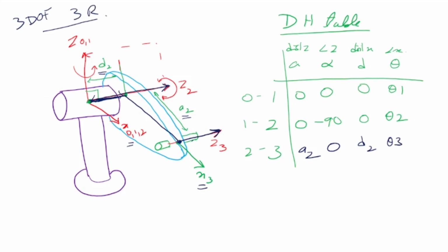Okay, so today we'll end here. Today we discussed DH parameters, and using DH parameters how we can make the various transformation matrices. After making the transformation matrices, we need to multiply all the matrices. After you multiply the matrices, you will get the final matrix, which will give you the relation between the end effector position and the end effector orientation.